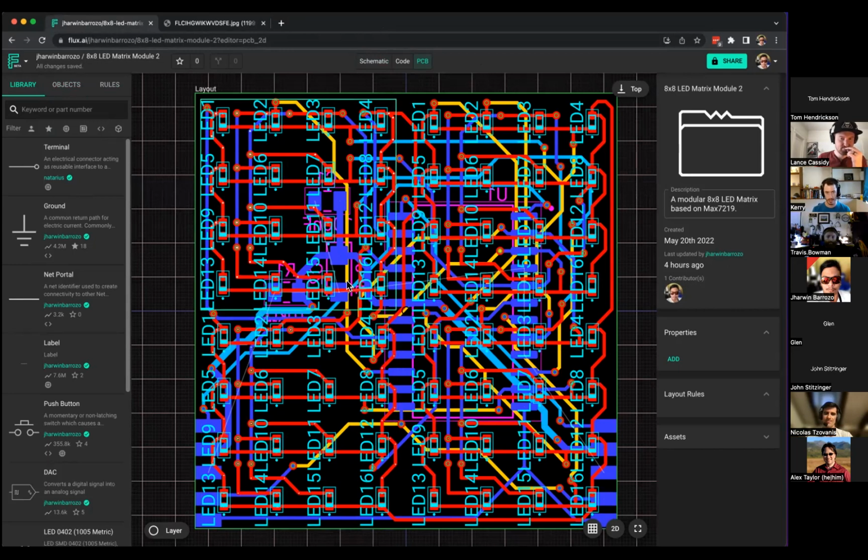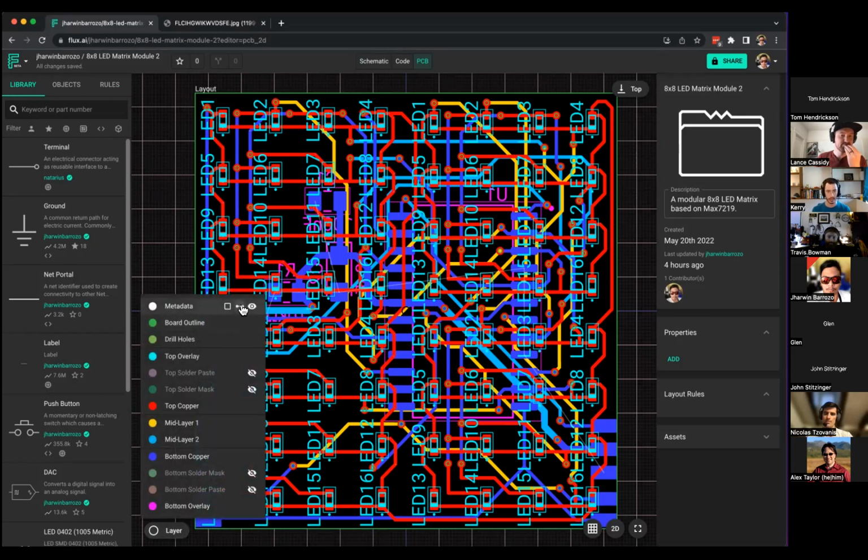I could still see a couple of errors here, 1, 2, 3. Yeah, those are the ground pads. I intentionally did not trace that one because maybe in the next couple of weeks we will have the copper fill. I'm not sure when that would land, but it's already a work in progress. So once that lands, I'm just going to visit this project again, and those pads will be connected from here to there. If we activate and deactivate the airwire, we could see where those are. So we're just going to leave that one not connected as of the moment.